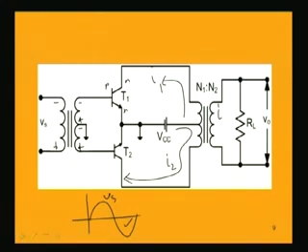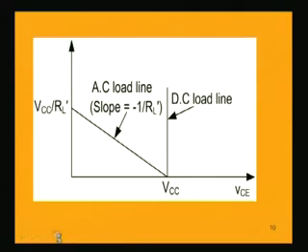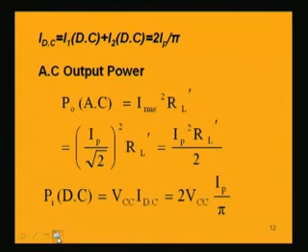The output power obtained across this load resistance RL is a resistive load, so it is current square multiplied by RL. That current must be the RMS value of the AC current. Whenever we find the average power in AC, we take the RMS value. So I square R, but that I should be the RMS value. That is why we write I RMS square into RL dash.